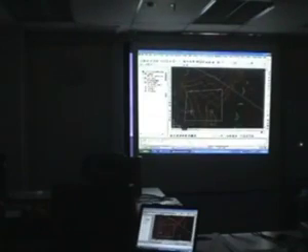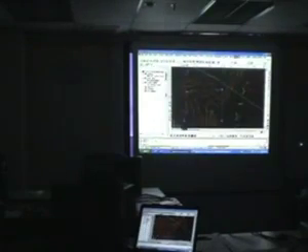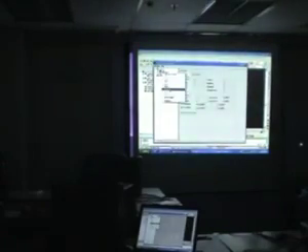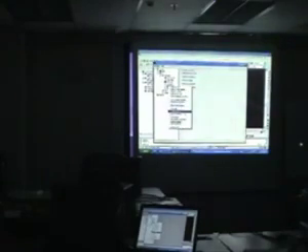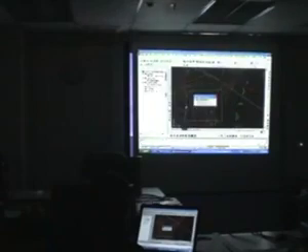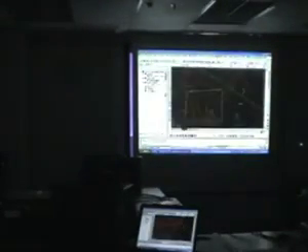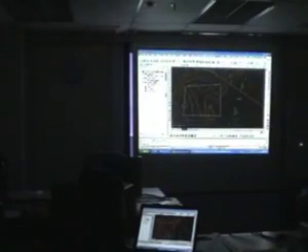This is a very simple platform, so I'm just going to draw a square at 35 meters elevation. I'm just going to define this as my proposed level. Okay, no slopes, nothing. I add this in as a break line. So now we already have a platform.